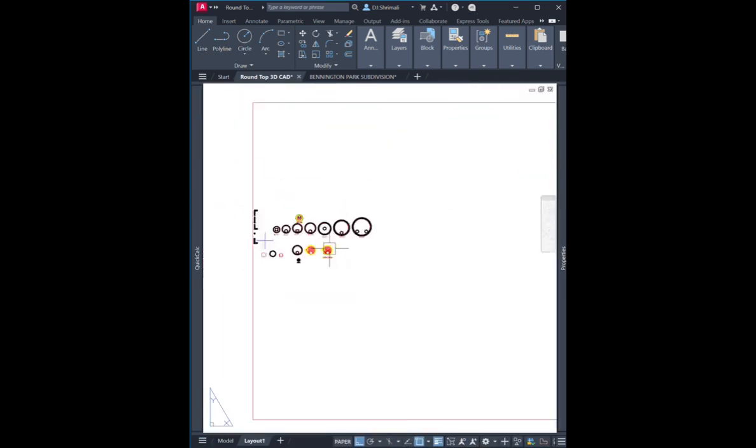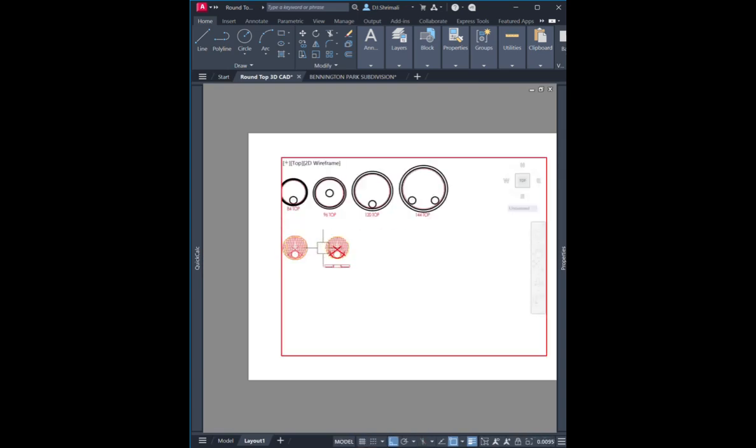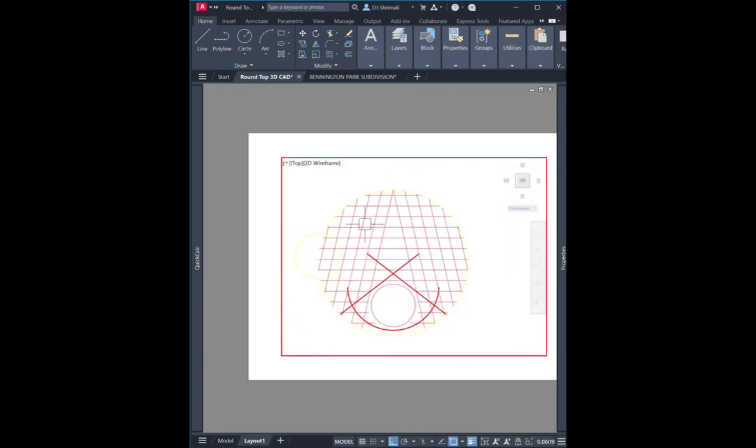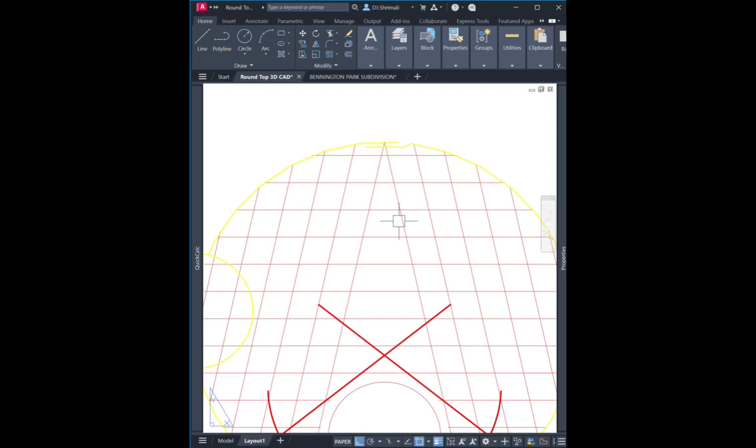Since you have the actual scaled rebar layout in the model view, you just create a viewport in a layout, and then just add dimensions to those rebars using the dim command. And always, when you click dim and press shift, it will give you aligned dimensions.